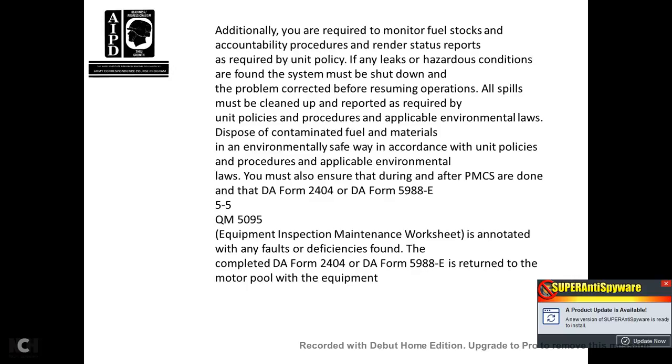Additionally, you are required to monitor the fuel stocks accountability procedure, rendering the status report as required in unit policy. If any leaking or hazardous conditions are found in the system, it should be shut down and properly corrected before resuming the operation. All spills must be cleaned up and reported as required in unit policies, procedures, and applicable environmental laws. Dispose of contaminated fuels and materials in an environmentally safe way in accordance with unit policy, procedures, and applicable environmental laws.